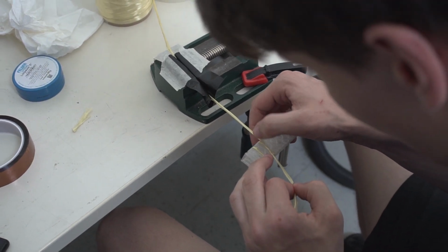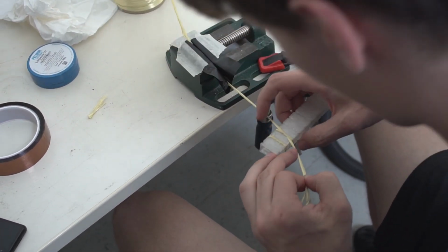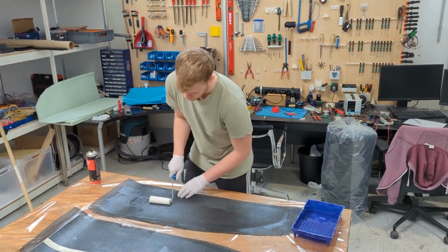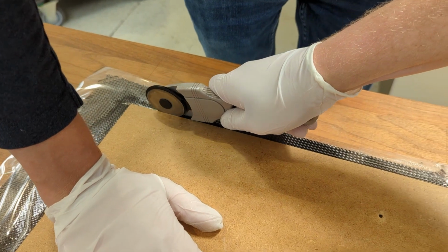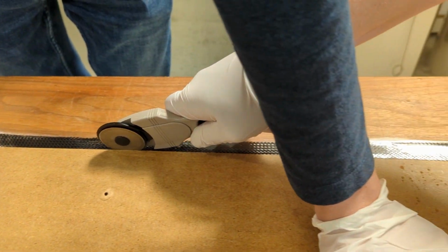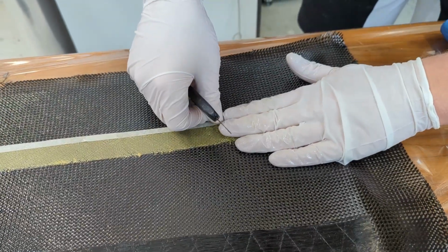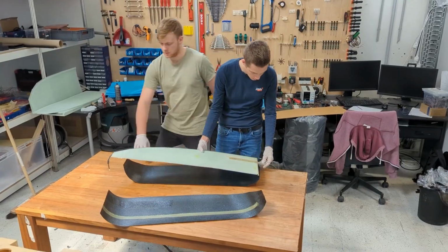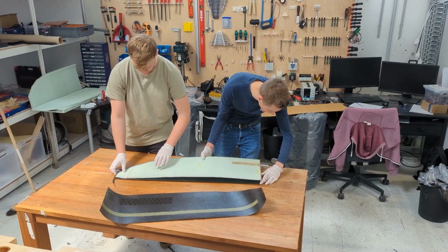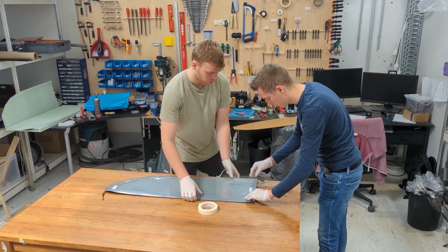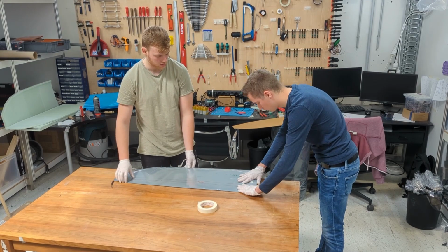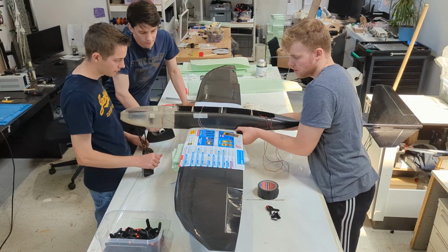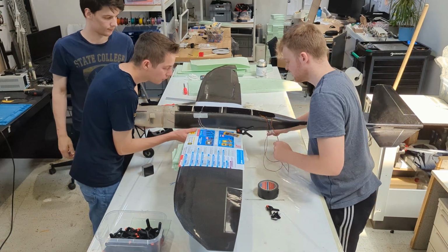To give the wing its strength, we covered it with carbon fiber cloth. The carbon fiber was first soaked in epoxy resin and then cut to size. A strip of aramid was added to the lower side of the wing. This would later serve as the hinge for the flaps and aileron. This layer was then put on the foam core and sandwiched between 2 plastic sheets. The wing was then cured in a vacuum bag. The vacuum ensures a good contact between the carbon fiber and the foam core, and the smooth surface of the plastic sheet is copied to the wing.